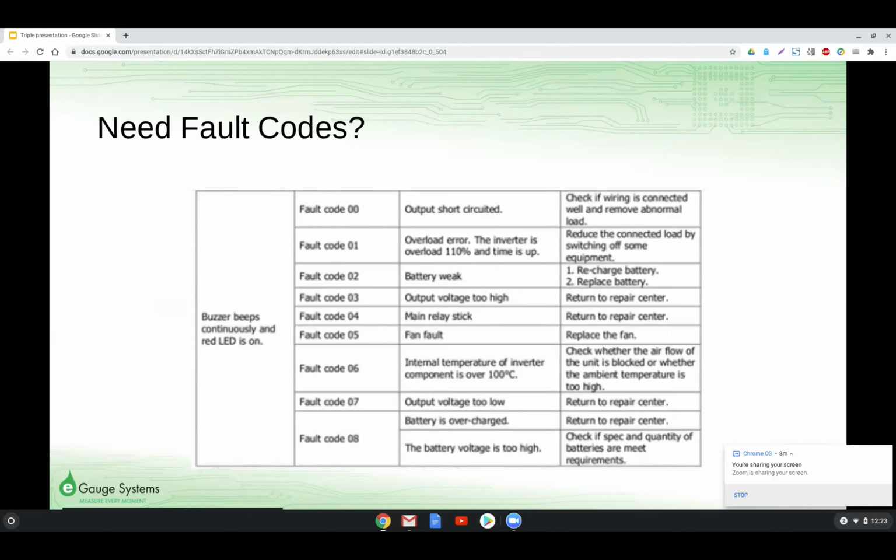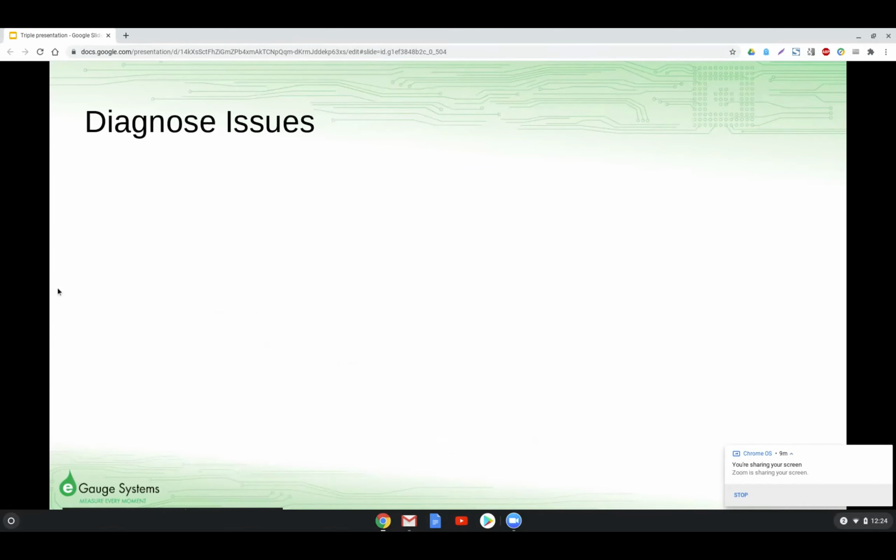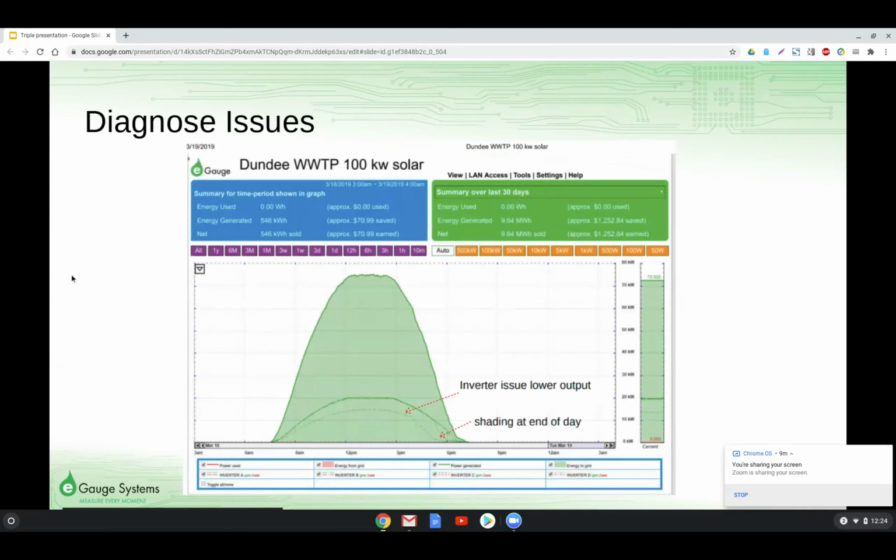These are all typical tools that customers can use to provide credibility to their customer. Another big thing right now is to show your customer, or to maintain your system properly, is to look at the fault codes. With eGauge, you can pull in any of the SunSpec certified inverters, have those fault codes set in your system and in your configuration, and be alerted when something goes wrong. In this case, you want to be able to pull that in and get real-time information so you can protect that ROI that you showed your customer.